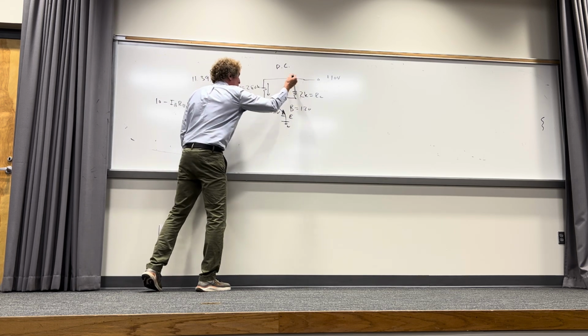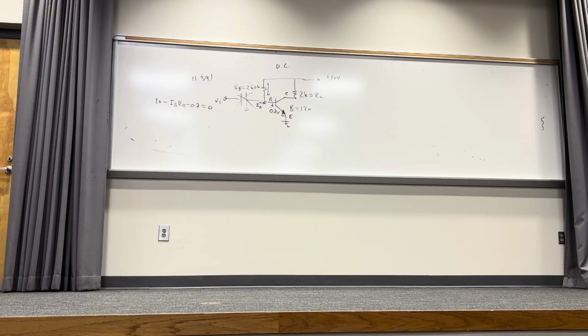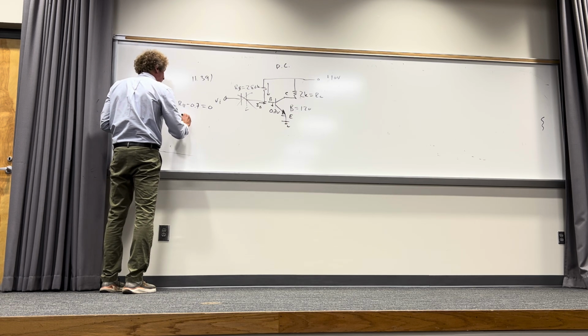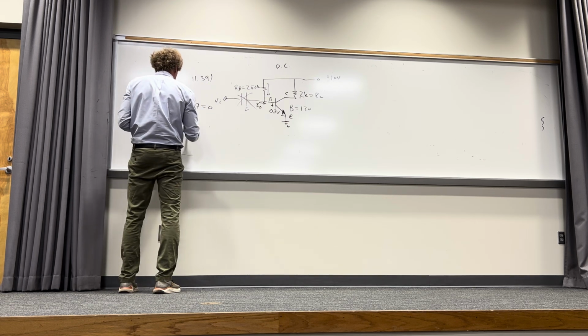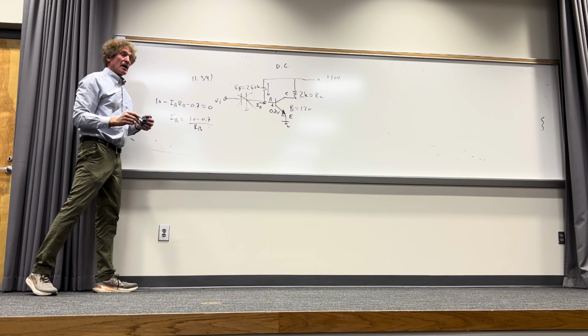This is a closed loop. I'm showing you the sum of the voltages around that closed loop must be 0. I didn't put all the wires connecting top and bottom. I just used the ground symbol. Everybody see that? If you do, just let me know. In the back, can you guys? Far back. Okay. So really I can say that IB here is just 10 minus 0.7 or 9.3 divided by RB. Everybody with me on that?